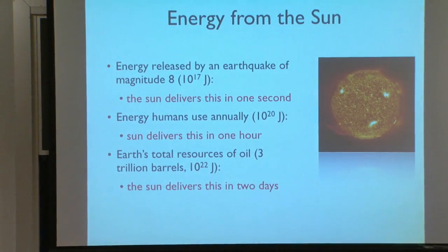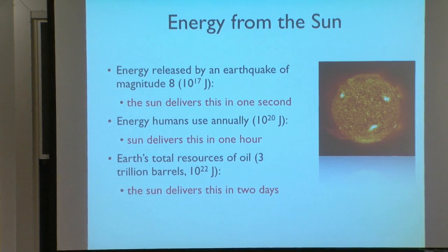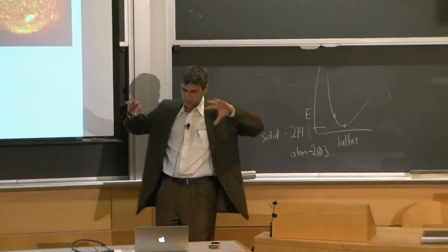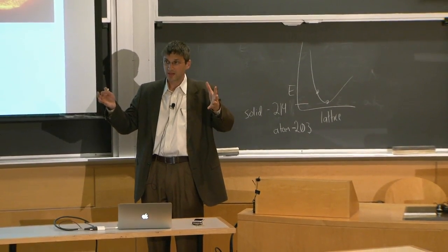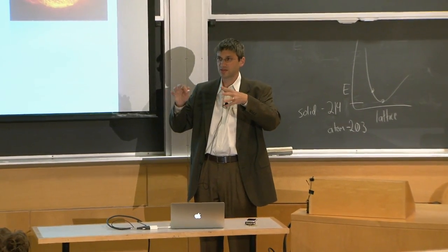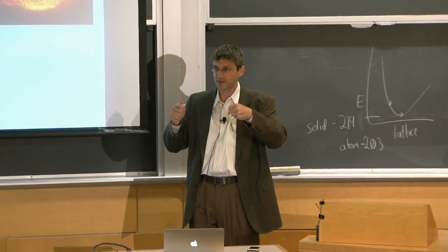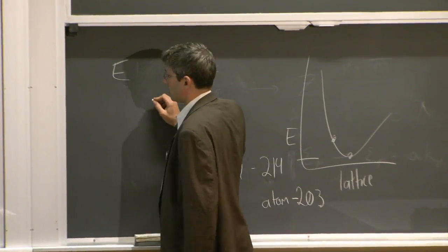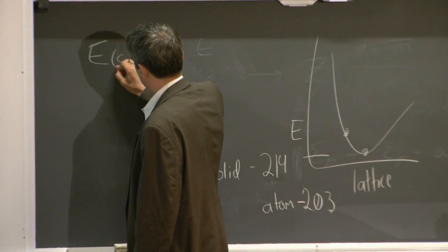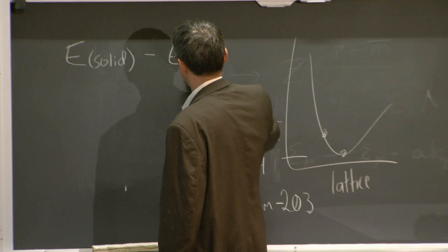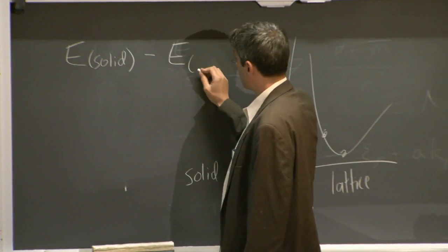There was a question up here. What's the physical definition of cohesive energy? So the cohesive energy really, the feeling is the glue between the atoms. That's the feeling definition. It's how strongly they're glued together. The actual quantitative definition is it's the energy of the solid minus the energy of the constituent parts, which in this case are atoms.